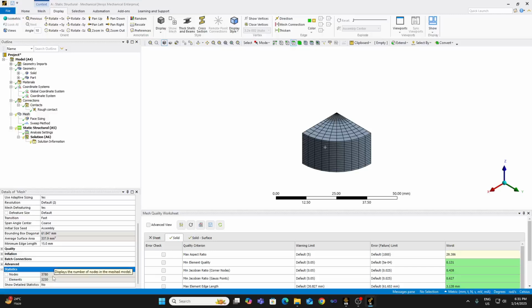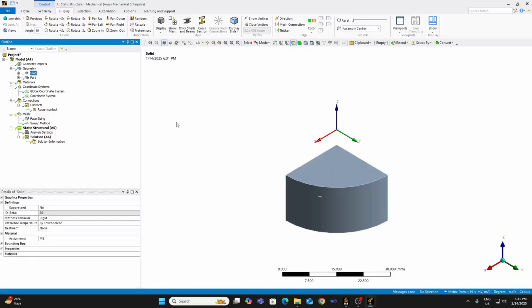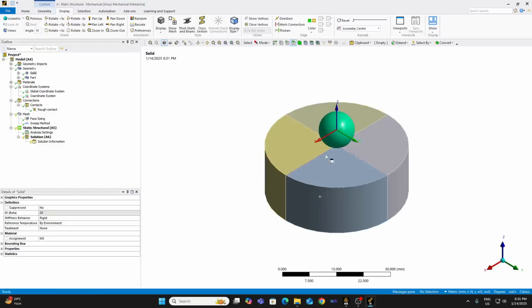So we are pretty low with the number of nodes, only about 4,000 nodes. With all the geometries being meshed, we'll only have around 16 to 17,000 elements. By the way, the rigid body will also be meshed, which is not being shown here. So let me just show all the bodies, but only its surface will be meshed because it has contact with the remaining set of bodies. If it didn't even have contact, there would be no mesh at all, because it would only be modeled with a point mass. But anyway, we have not inserted the density, so it also doesn't make any sense, because we are doing a static problem without any kind of gravity or any other type of body force.